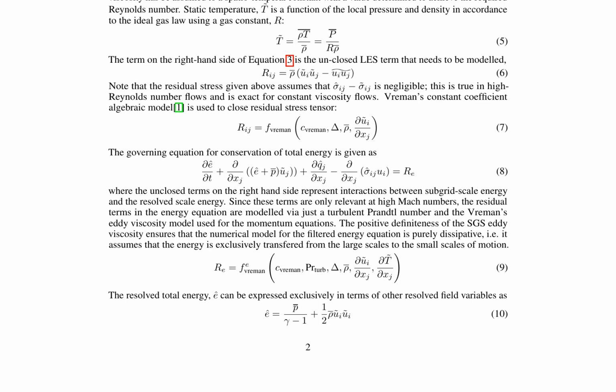Residual terms are modeled via turbulent Prandtl number and the Vreman eddy viscosity model. This methodology is particularly suited for high Reynolds number flows, ensuring numerical stability and accuracy.